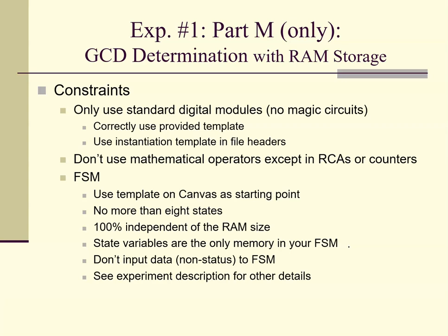The FSM should be 100% independent of the ROM and RAM sizes. The state variable should be the only memory in your FSM. Don't put data of any type into your FSM, because it makes your FSM non-generic. The only thing you're going to input to your FSM is status data.